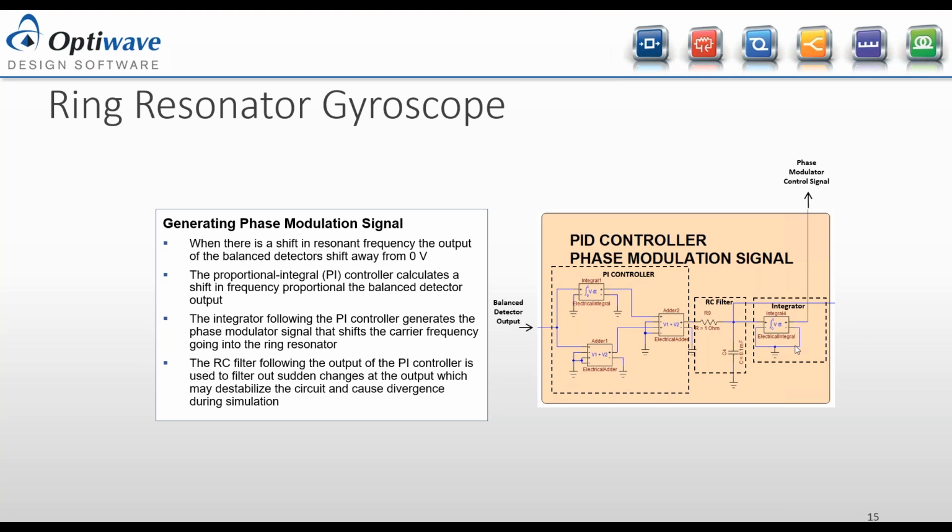And finally, we have our integrator here, because using the controller, I'm actually changing the frequency. A constant change in frequency is equal to a linear increase in phase. So because we're modulating the phase, I'm integrating the output, as it's the change in frequency.